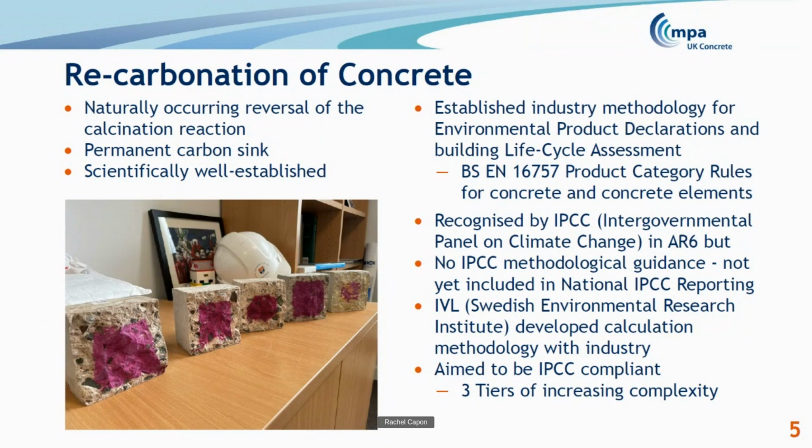It's scientifically well established, and we do have established industry methodologies in EN 16757, the product category rules for concrete and concrete elements. We have established methodologies for calculating the carbonation for the purposes of EPDs and building life cycle assessments.